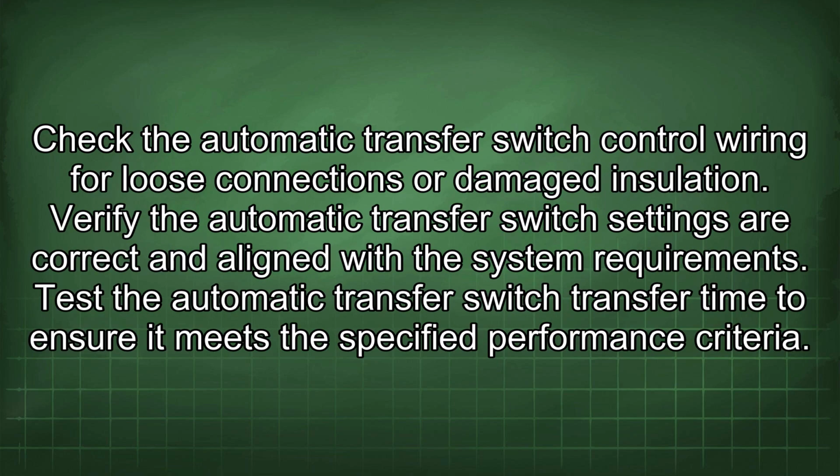Check the automatic transfer switch control wiring for loose connections or damaged insulation. Verify the automatic transfer switch settings are correct and aligned with the system requirements. Test the automatic transfer switch transfer time to ensure it meets the specified performance criteria.